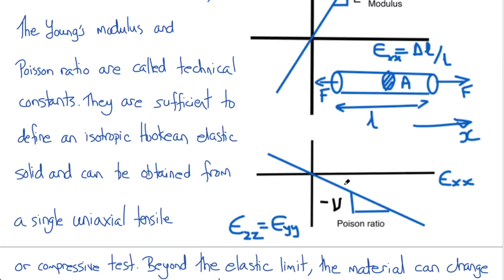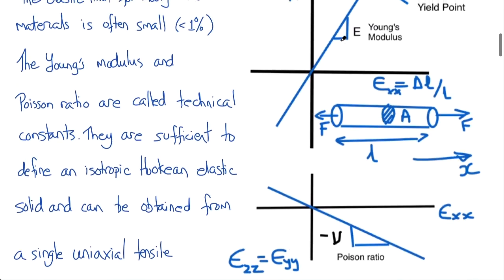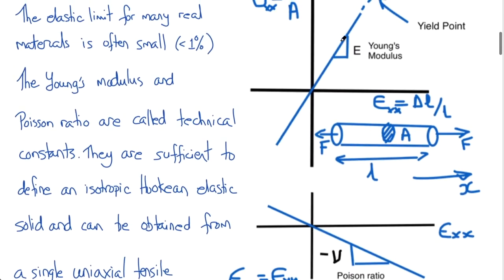Now, it's important to realize, as we've pointed out before, that the context of the loading, not just the material itself, determines the accuracy of the assumption of linear elasticity. You can see that in linearly elastic materials, this approximation holds well, but for small strains, typically considerably less than 1%.